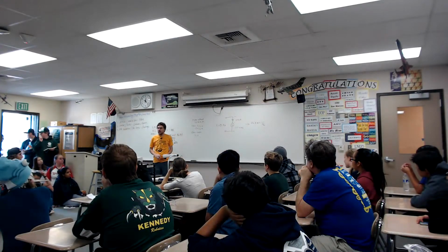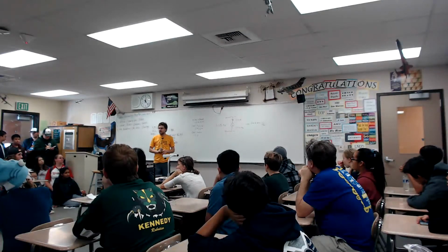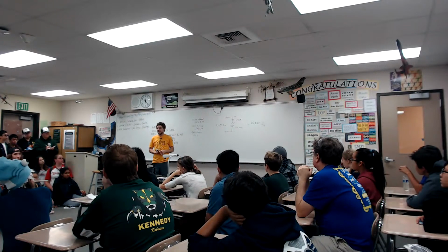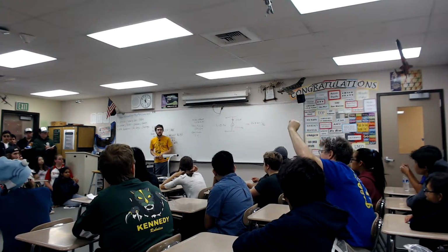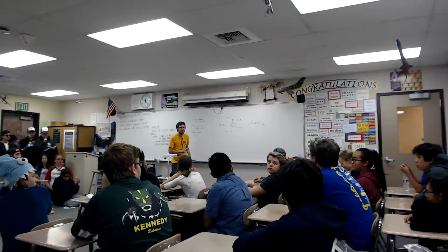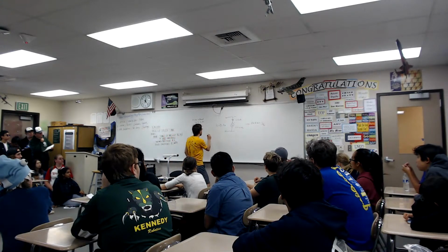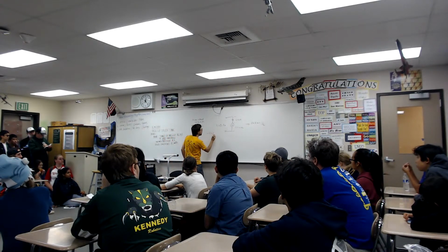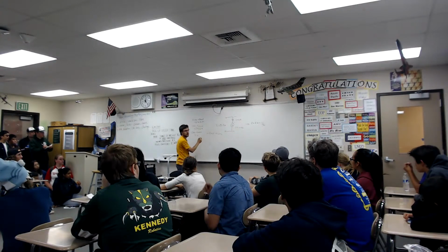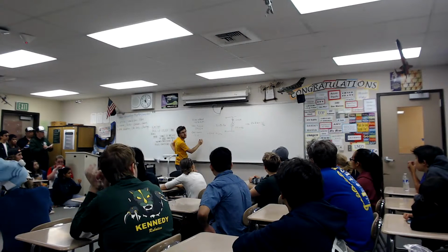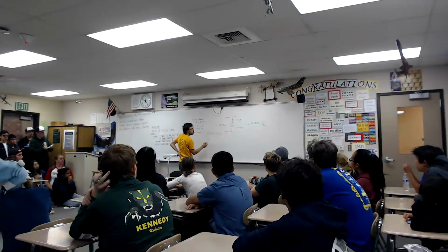So can anyone see how to get one of those numbers? Volunteer. All right, when it's stalled, omega is 0. So then we can do this. What would the other numbers be? So V equals IR. Are they talking 12 volts? Yep.